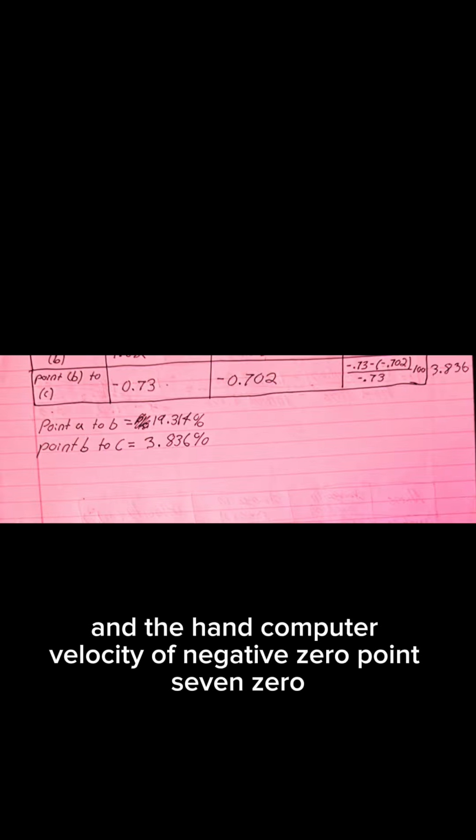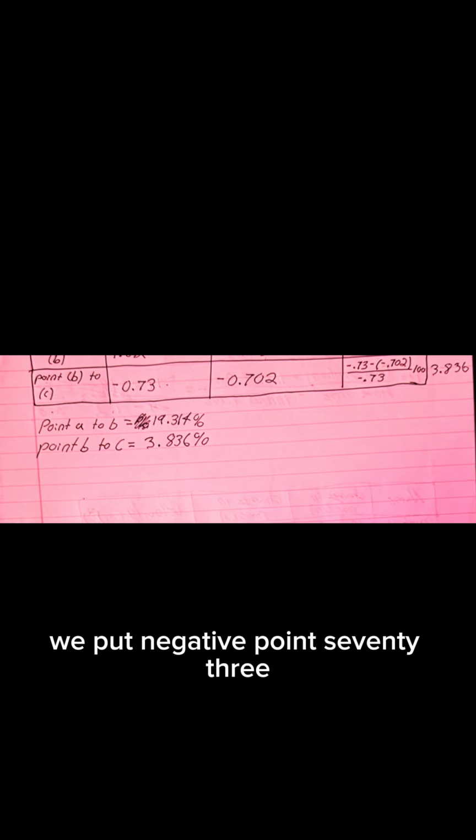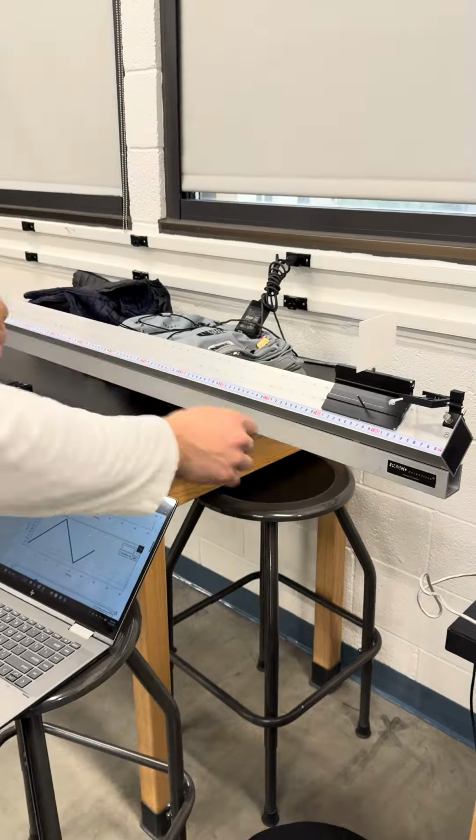For point B to point C, we had the mean velocity value of negative 0.73 and the hand computed velocity of negative 0.702 meters per second. Using the percent difference equation, we put negative 0.73 minus negative 0.702 divided by negative 0.73 times 100, which gave us a total of 3.836%.